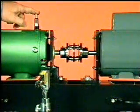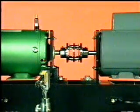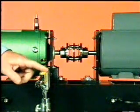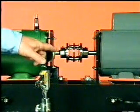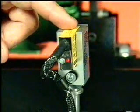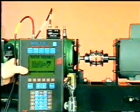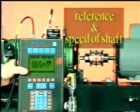The reference position can be a keyway or any other location, but is most often simply a position marked with reflective tape. A phototack such as this is then used, which sends a light beam to the rotor. When it strikes the reflective tape, the light is sent back to the phototack, which then sends a signal or pulse out to an analyzer. The tack pulse is then used as the reference location and speed of the shaft.